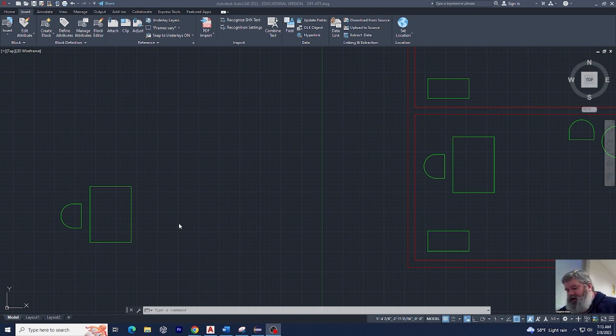Today, you're going to learn how to use the block command to transform objects into blocks, be able to use the insert and multiple insert commands, know the color, line type, and line weight of blocks are based on conditions of when the block is made, be able to convert blocks to individual objects with explode, be able to use the W block to prepare DWG files, be able to redefine and globally change previously inserted blocks, and be able to use Design Center. So that's what you're going to learn today.